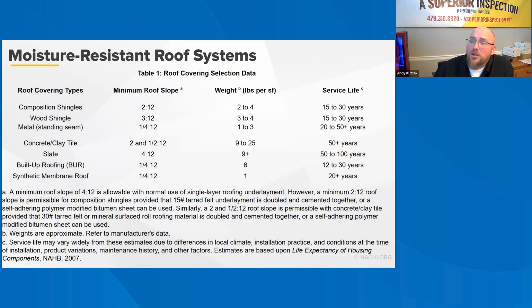By contrast, low slope systems are designed as waterproof roof systems and use a roof covering designed for slopes as low as 1/4:12, quarter inch fall per 12 inches. While low slope roofs are commonly known as flat roofs, an actual flat roof surface is a design mistake. There should always be some slope, whether it be to the exterior or to an interior drain. Inspectors should report a flat roof that is actually flat as being defective.